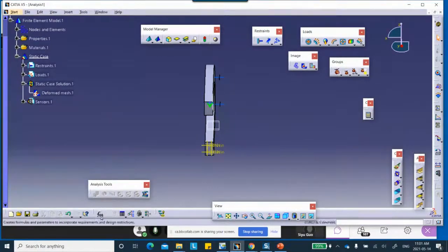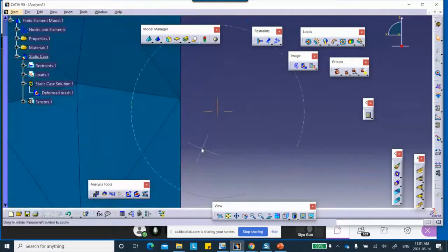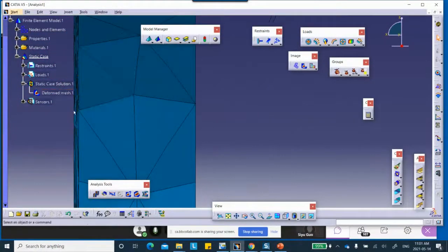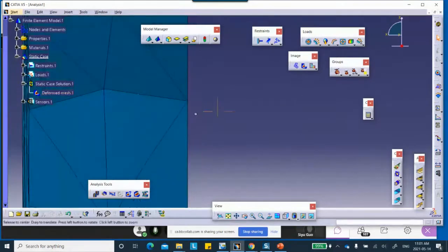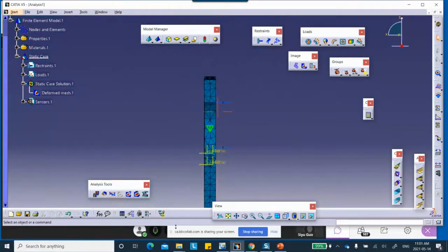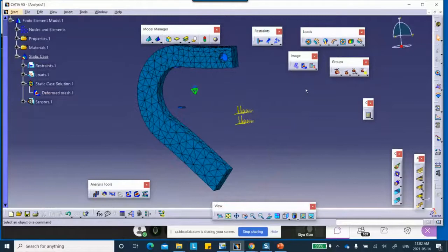Now, if you look at the view from the front, or the side actually, and you look at the deflection, it doesn't matter how much you zoom in. The left side does not go to the left. You see, this one will shrink because it's a free surface. And before, since I didn't put any constraint on the other side, roller support or surface slider, it also went sideways. But regardless of how much you zoom in, within numerical error, that's good. Okay, 1 mark. Von Mises stress.